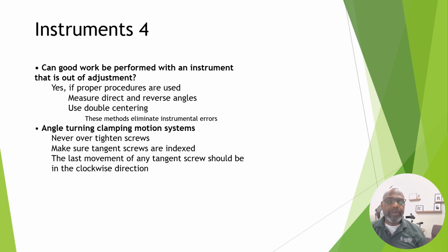Some of the basic practices: reading the owner's manual, setting things up correctly, putting the tripod in the ground securely, making sure it's balanced and level, and setting up over a point. If it's a transit, use a plumb bob to balance and make sure you're finding that point, that everything is exactly the way you want it.